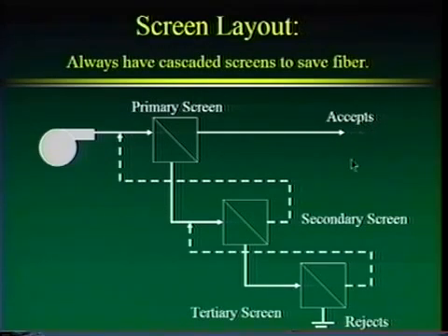So that is a possibility. It's used a lot. In the book it shows a whole bunch of different ways that this can be arranged. This is the most conservative way to run your system. If you want to take some chances, then you can circumvent. For instance, the accepts of the tertiary screen could go to the feed of the primary screen. Or actually, there are different ways to pump it up, and it's always a question about how much throughput you want, or how confident you want to be that these accepts are clean. So, very good point.